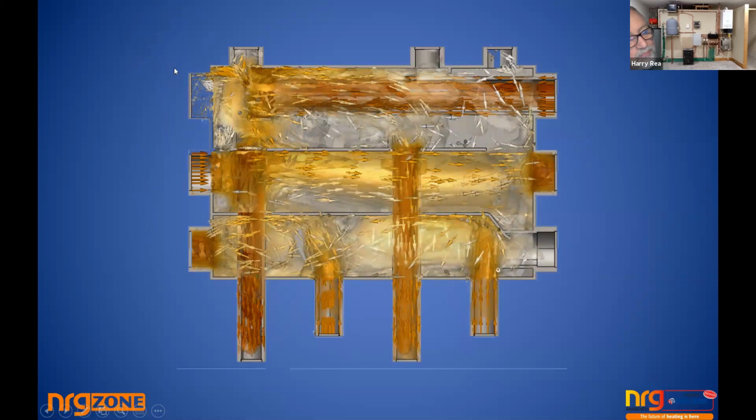You size your pump on your hot water cylinder for 20 litres a minute. Now the hot water is taking all of the high temperature water from the gas boiler, and the heat pump has to fill the gap, because if there's a vacuum created here because water is being drawn away, something must come back and fix it. The only water available is the heat pump. The heat pump and whatever residual water from the gas boiler, because your maths must be right, will feed the zones.